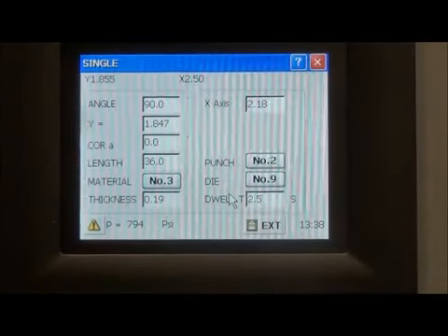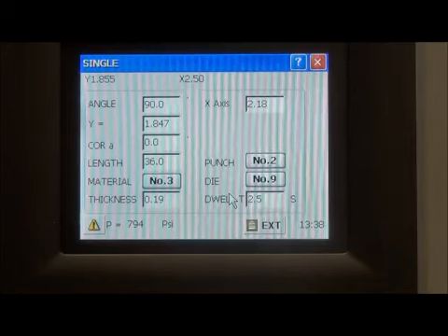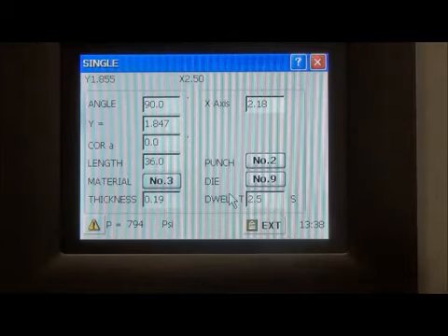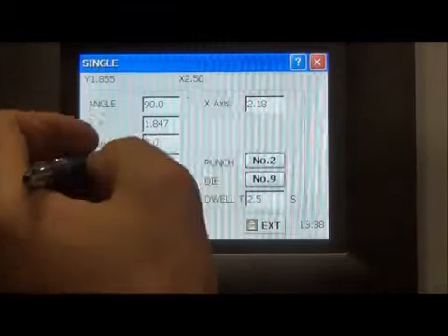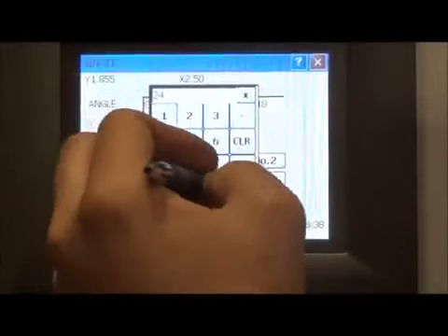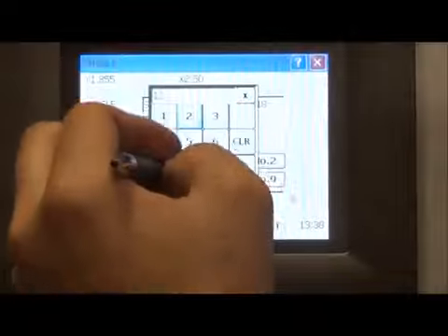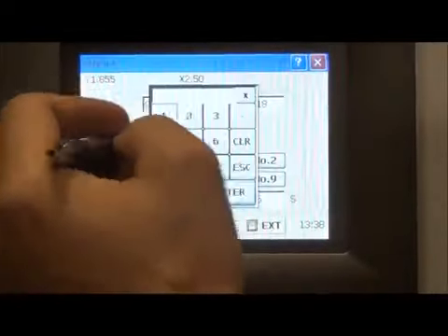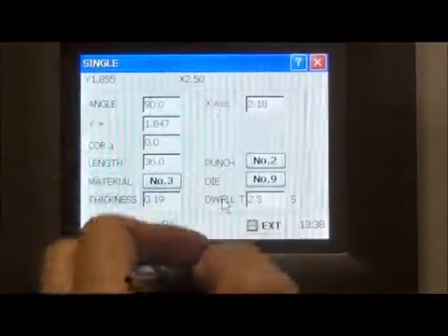Once you make the bend and see whether or not it's 90 degrees or not, you can then begin to adjust your angle correction, either positively or negatively, depending upon which way you need to further adjust your angle. You'd put in the length of the material. Could be 24 inches, could be 120 inches. It all depends on whatever it is that you're bending.